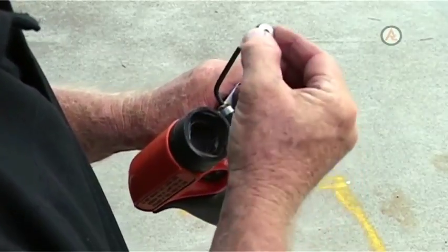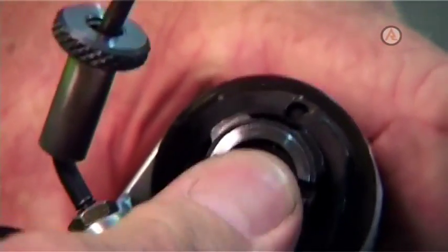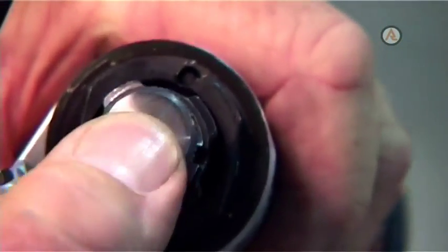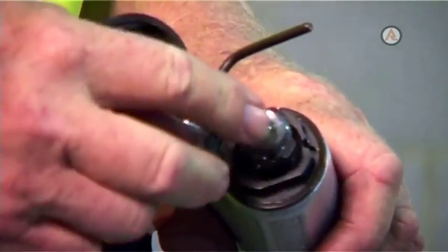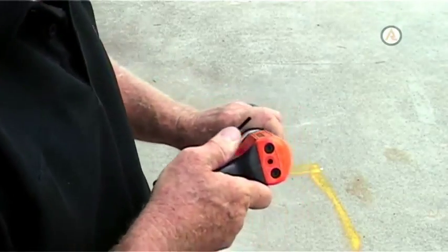Then remove the breech plug and check that the barrel is clear. Insert the fastener, point first, into the barrel using finger pressure. Then replace the breech plug and insert a cartridge into the breech plug. Then close the tool. The tool is now loaded and ready for use.